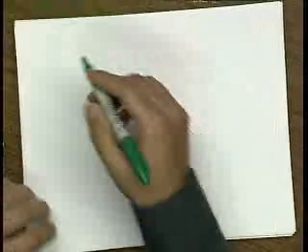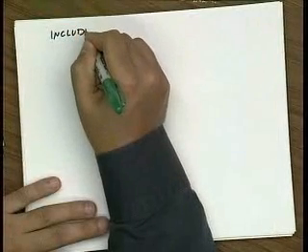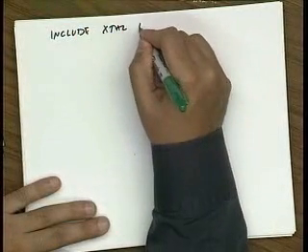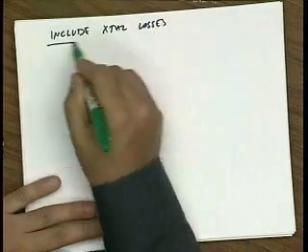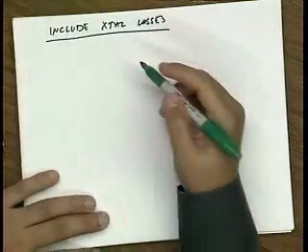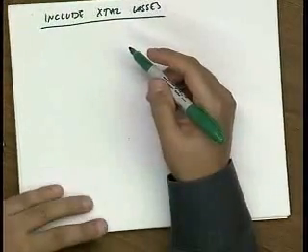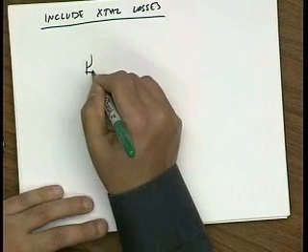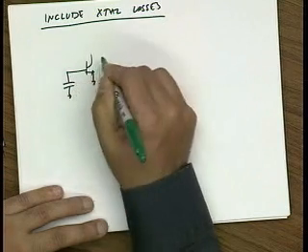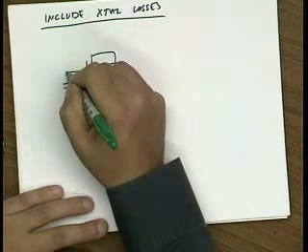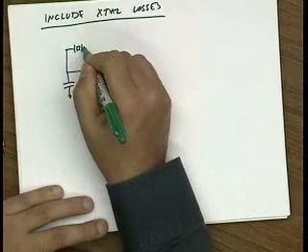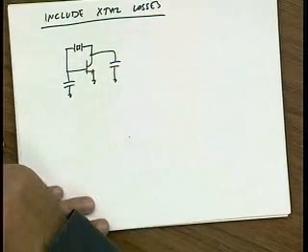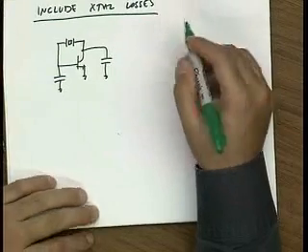All right, so let's look at the losses, which are actually really important because they ultimately will lower the Q of our circuit. So let's go back to this Pierce oscillator. Again, we're looking at the Pierce because it's a popular topology, but by no means do you have to design an oscillator that looks like this.